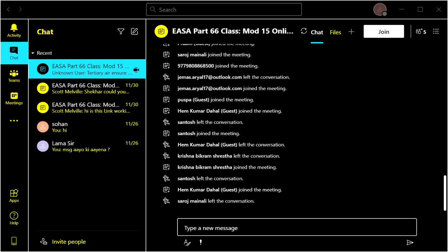What we have instead is a pressure differential switch, which monitors the pressure upstream and downstream in the high pressure system. If that gets too low, a warning light in the cockpit will come on to let the pilot know that there's something wrong with the oil system.